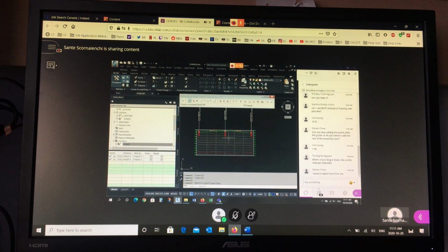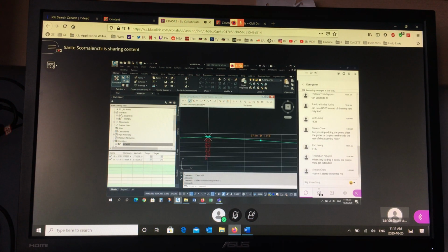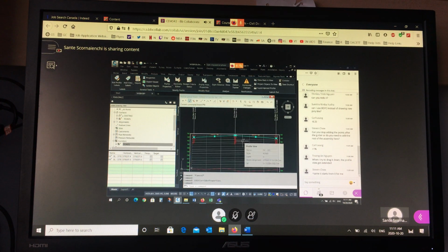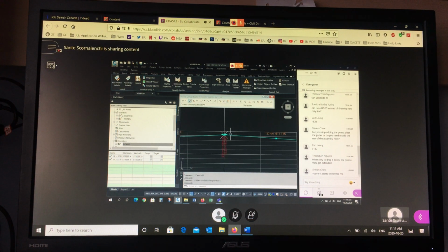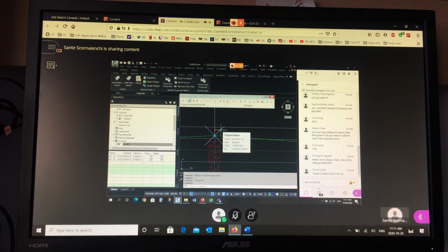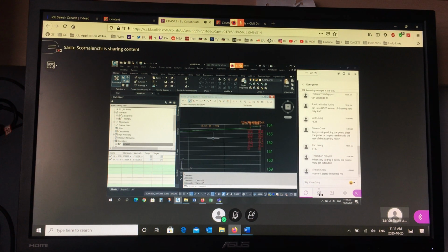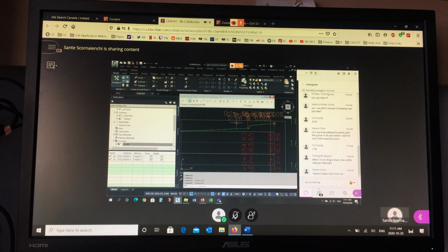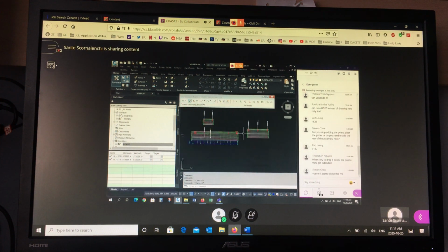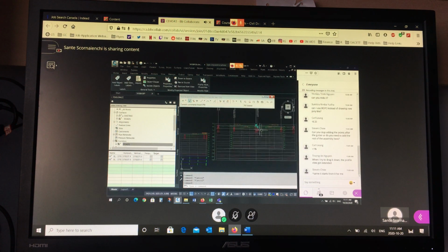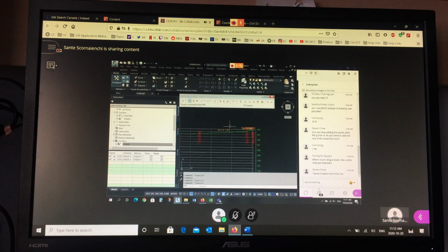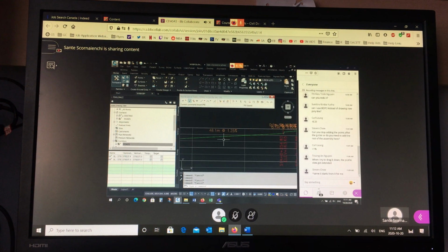Okay. Now because this profile design connects the dots, it's not dynamically linked. So if this changes, if the elevation of this point changes because the surface changed, you'd have to adjust this manually. Okay, so for instance, if I go to my profile, suppose I've made a mistake here. If I change the elevation of the profile here, I need to reproject this here, and so on. So suppose I wanted 2%. So let me redo this, just as an example.